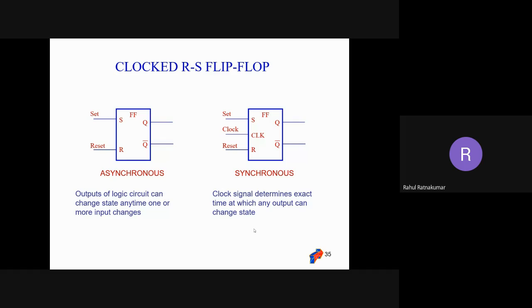We are on a global clock which controls all the input and output. So we have a lot of handshaking signals. Acknowledge, we know from modems, if you studied modems, you know there's a request. Shall I send? Request, acknowledge, sending data, acknowledge again, acknowledge from the receiver that I received. So that is called handshaking signals. If we don't have a synchronous clock, we need a lot of asynchronous signals like handshaking signals.